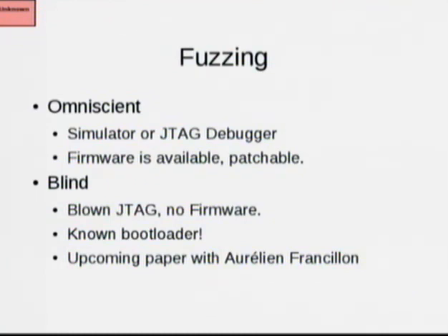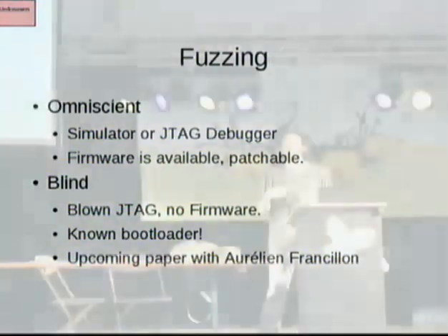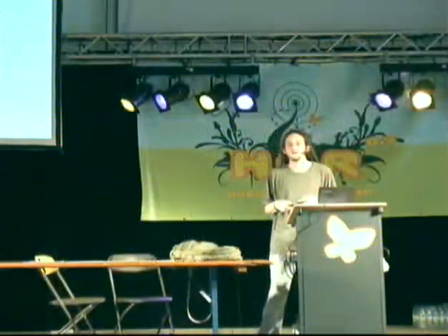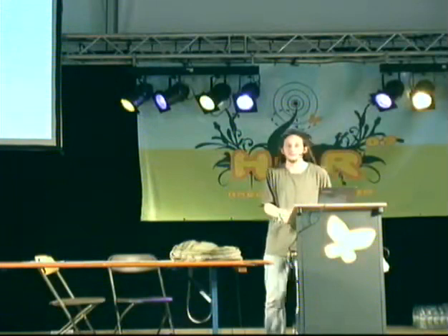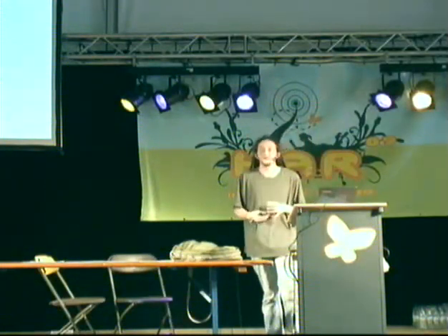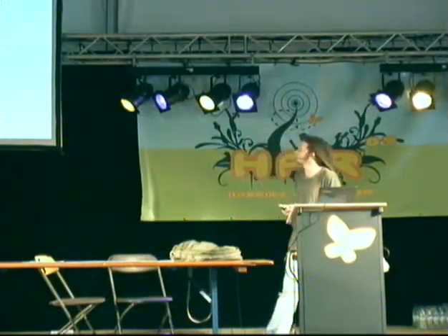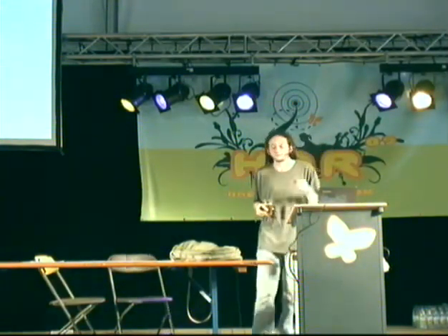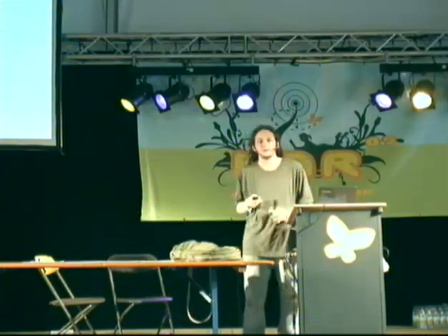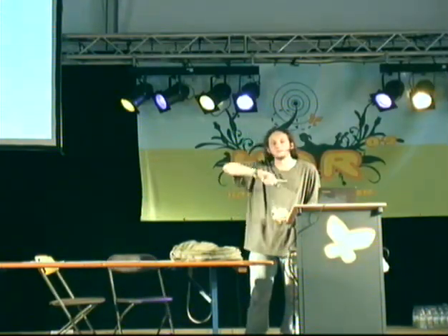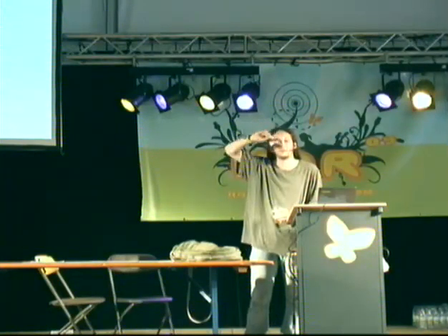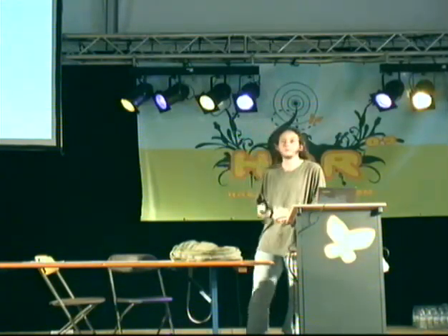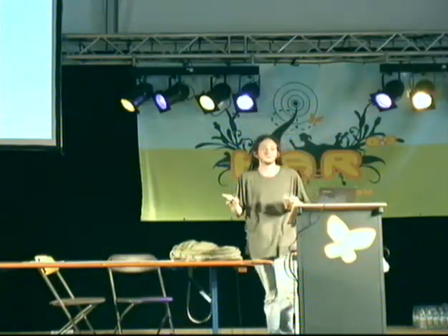To do this, you start injecting fragments that might reset the chip. And you keep doing it until you can make it return into the bootloader. You know it's in the bootloader because it's masked ROM. It's the same on every chip. So when I was attacking one of these with Aurélien Francione, we started sending random packets. And the random packets would have just repeated fields of the entry point of the bootloader. And then we just waited for the bootloader to start up and say hello.